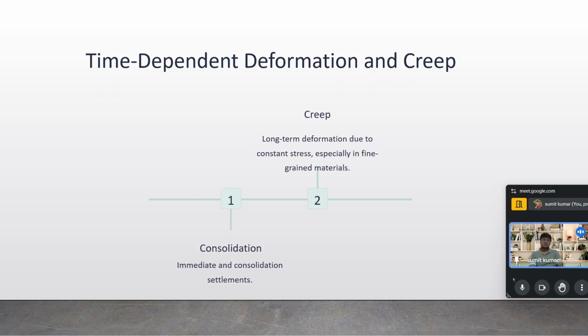Yeah, this is the correct question. So suppose we differentiate between sandy soil and clay soil. In sand, water gets dissipated very quickly, as we have discussed earlier during the triaxial test. It allows the water to flow out. Basically, in sandy soil, the pores are sufficiently large to move the water out. So in sand, the water flows out very quickly. So we can say that the consolidation settlement takes place during the construction work only.